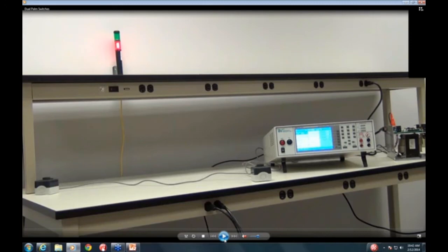So what I'm doing here instead is using two-hand controls. You can see them on the left-hand side near the middle of that test bench. I have them spread apart, much wider than 21 inches. You'll see in the video I'm standing kind of awkwardly off to the side, but that's because I wanted to give you guys a good feel for what I'm doing here and show you.